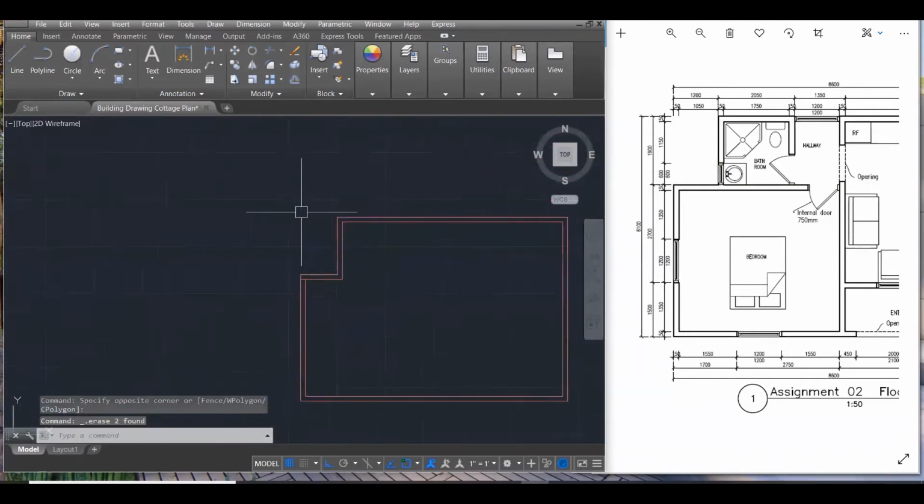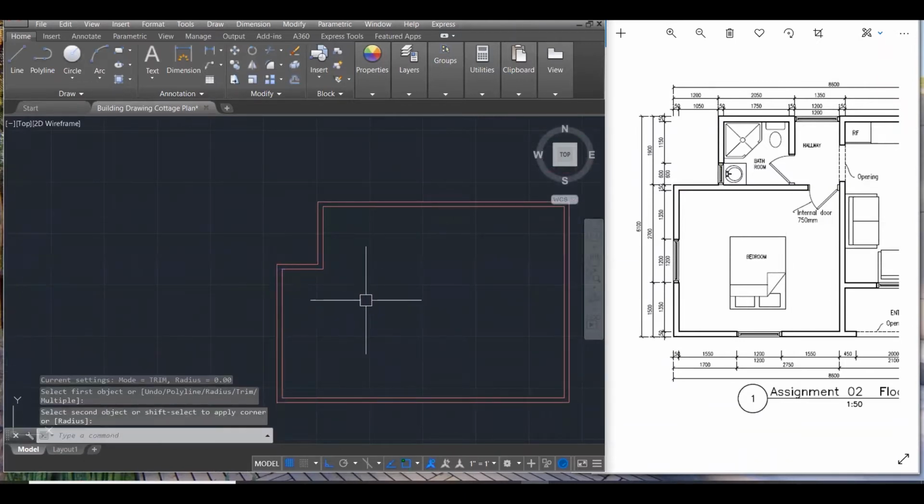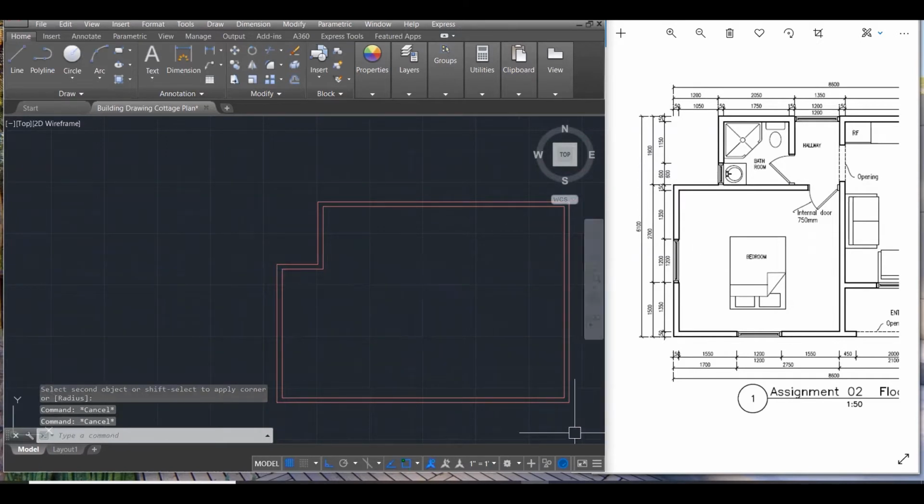Cool. So that's the shape there. Nothing too hard there. What can we do now from here? We need to focus on putting in these internal walls. So let us leave it there for now, and then I'm going to put in this wall. How do I find the information for this wall? Well, it says here I can offset 150. I already got that. So I can offset 1550, 1200, and 1550 again, and I should be able to get smack on to that line. So I can come right here, offset 1550, 1200, and then 1550 again.